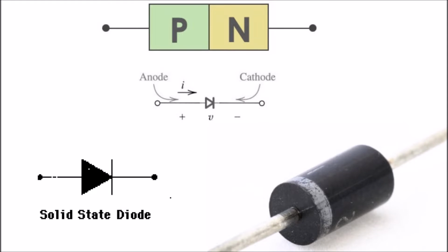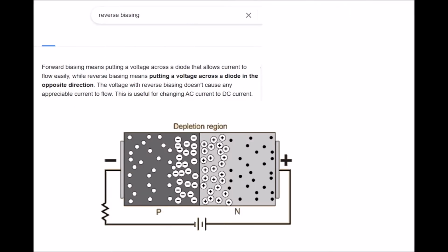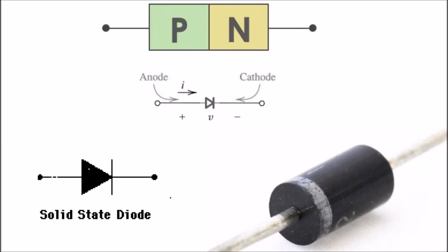To recap, in other words, a diode is a two-lead semiconductor. It behaves like a one-way gate for current flow. When a diode's anode is made more positive than its cathode, current is permitted to flow. What has just been described is a condition called forward biasing. The opposite condition is called reverse biasing. When the polarities are reversed, the diode acts to block current flow.